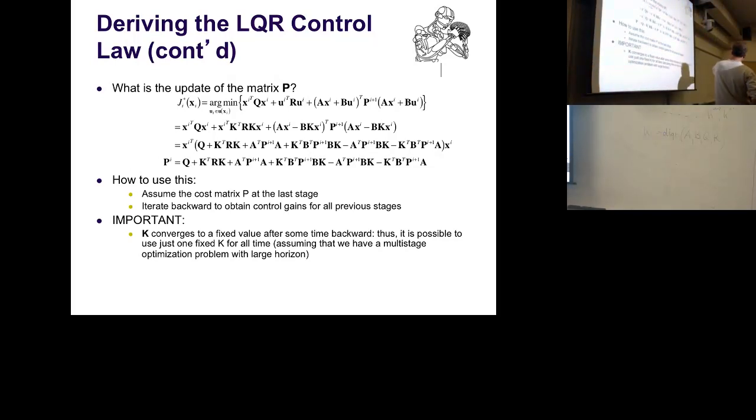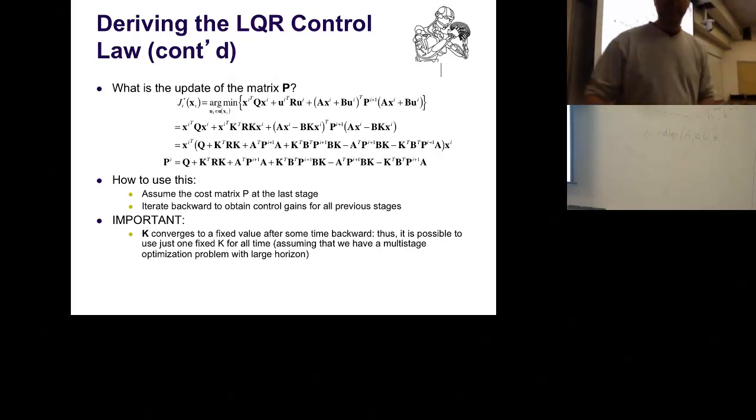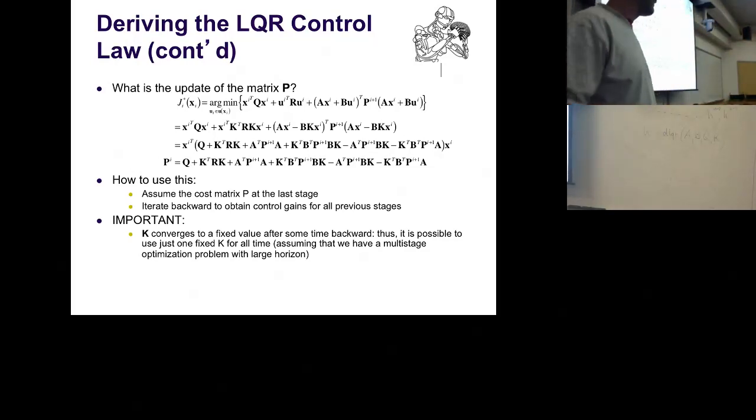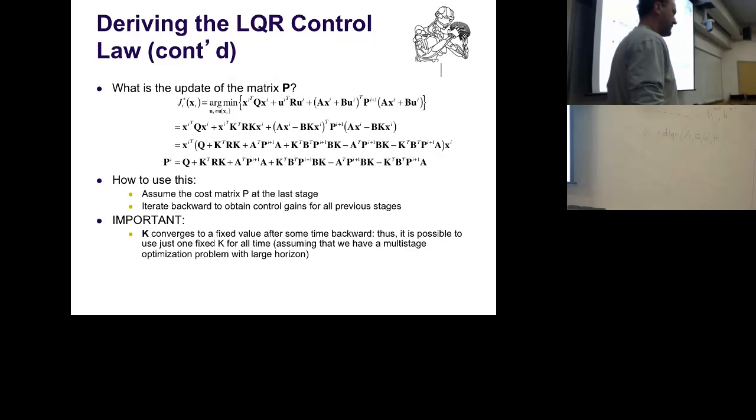You do have, and this is very important, you do have to play with Q and R values. And you will see big differences in how you set them. There's some intuition, and unfortunately, it's not fully automated at this moment of time. The R is weights of the commands. The Q is weights of the state.